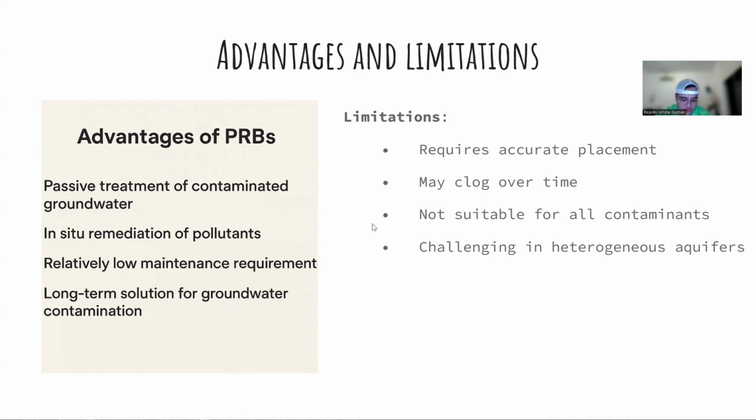That is an in situ treatment zone of reactive material placed in the path of a contaminated groundwater plume as the groundwater flows passively through the barrier under natural hydraulic gradients. Contaminants are removed via physical, chemical, or biological reaction.